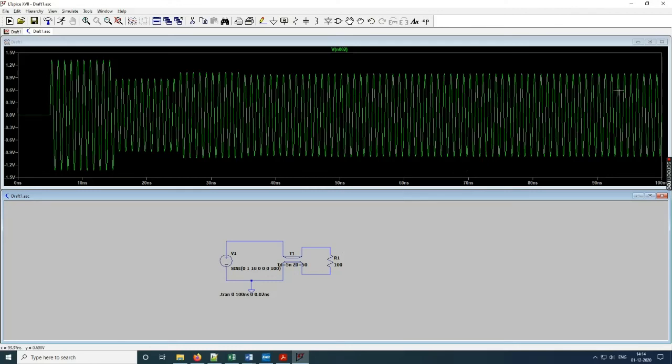If you look at some long time after 0, let us say 100 nanoseconds, you will see that the magnitude of this voltage is very, very close to 1 volt. What this means is, because there is no source resistance and the transmission line is lossless, the wave is sent from the source to the load without any loss.